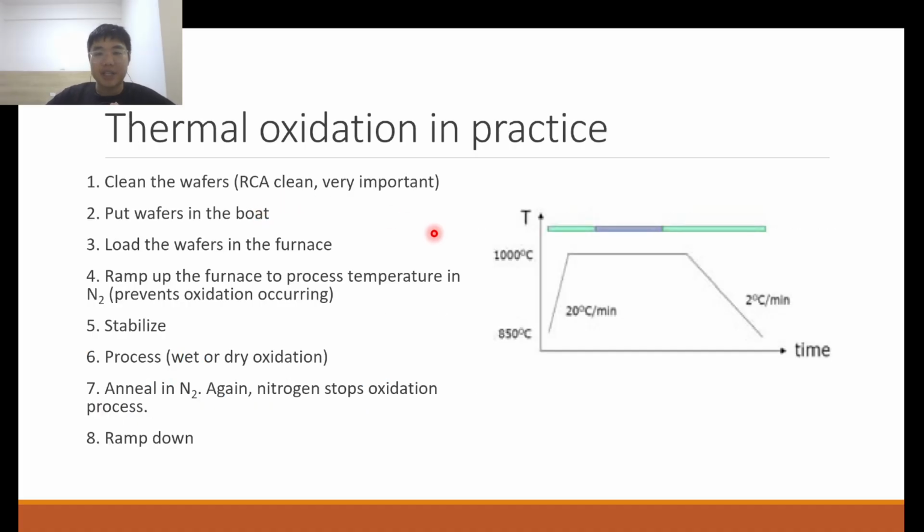And so how is thermal oxidation actually conducted in practice? So it's very important that we first clean the wafers, right? Clean the wafers with something called RCA clean, which I think I'll cover in a future video on wafer cleaning, right?